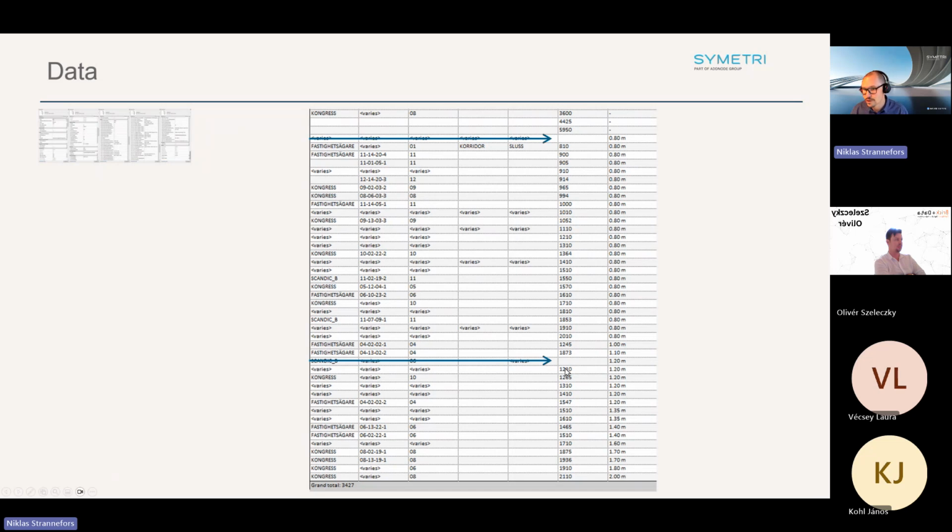Same with this one. This one is not going to manage at all, because this is the min clear width. This is the width, just the width of the door. But just doing a head count, we know this one is maybe not going to make it. But this is the architect's job. We provided the requirements. Now it's very easy for them to check, check, check, check. And when they're done, we can do the same kind of schedules and do the same check and say this door, this specific door. So instead of rechecking our requirements data, we just check the doors, because we're pushing all the information on the door.